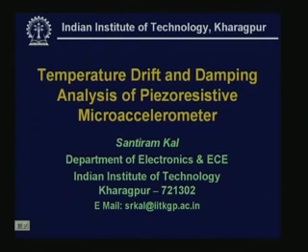The most important point is the temperature drift, because the sensing element is made based on piezoresistive sensing, and the piezoresistance is a temperature sensitive element. Many times in many lectures I have emphasized that part. Now in this lecture we will discuss in a little more detail which parameters change with temperature, and because of that your output drifts from the desired value. That is the major topic of discussion in this lecture.